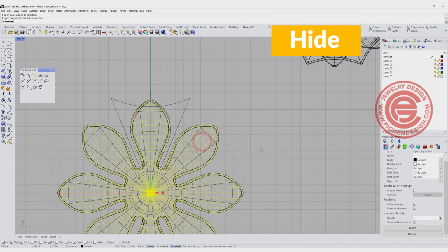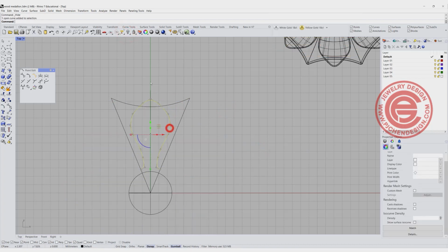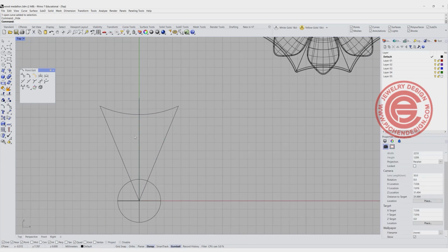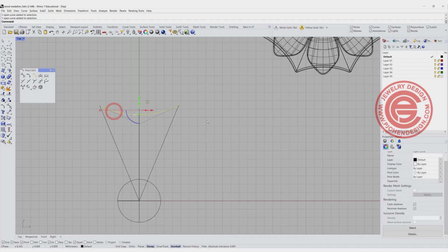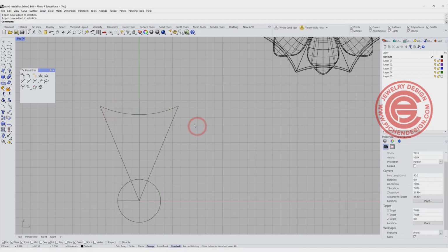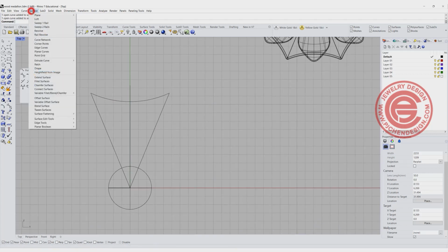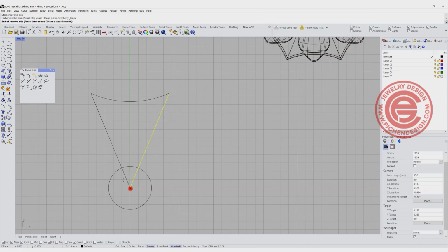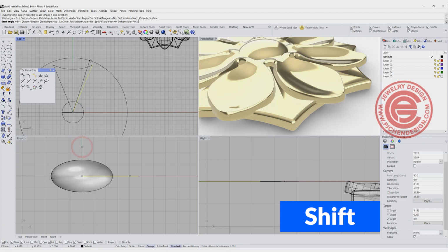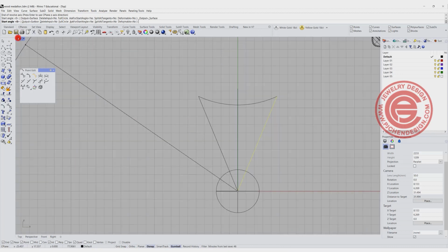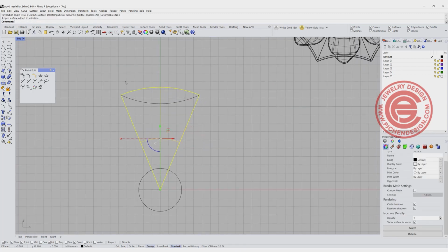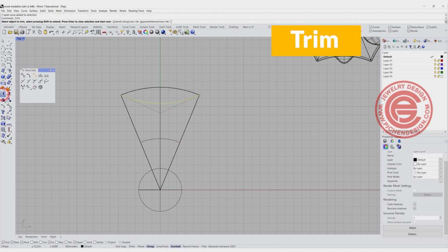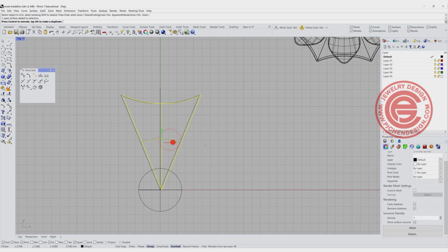All right. So I'm going to hide this guy right here, and let me hide this guy too to show you how to create this surface. Now you could use revolve and trim off the extra if that is going to work for you. Actually, let me show you directly. There are a few ways to make the surface, and they all work. It's just personal preference. You can use a revolve, and you can revolve from this in the center, holding the shift, click on the top, and let me enlarge this guy. You want to revolve from here to here, right? And of course, you get this surface and you don't need that extra, so you can use this one to trim off this one. Okay, so that's the way to get it from revolve.